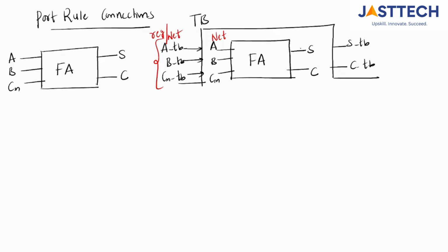Coming to the outputs of this design, they can be net or reg data type. And the outputs for the test bench should be net data type. So these are the port rule connections.